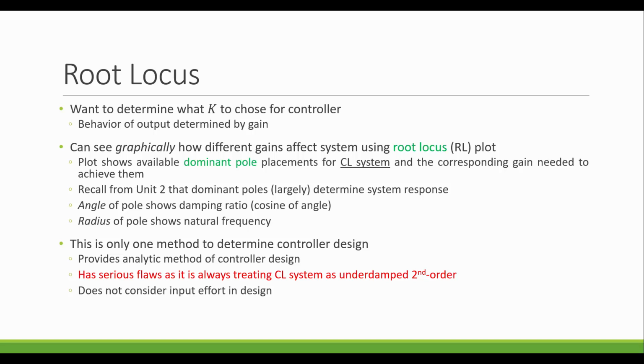That's not considered in this method. So it's going to give us kind of a basic idea sometimes for our design, and we might need to refine our design based on what this initial root locus method is going to get us. So with that being said, root locus is often a useful first step, but as we get into more complicated controllers, it's not going to get us all the way there.